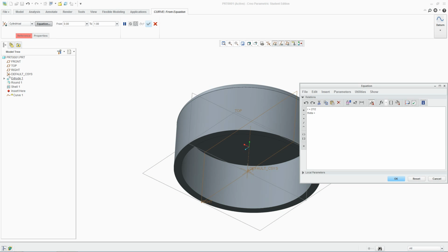you just gotta get your head around how to draw a curve as a cylindrical curve. So we just gotta have a parameter t and gotta times it by how many times it revolves around. I want to make it a bit more than 2, so about 360 times 2 and a bit more. I'll make that 800.